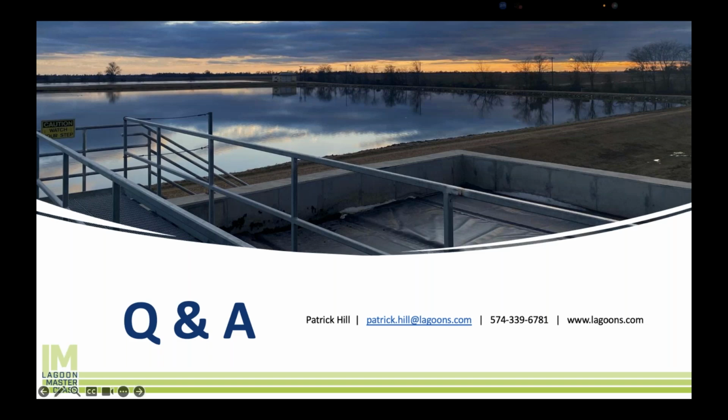From a labor and cost of material standpoint, there is a point at which the time and cost of putting the pond dye in, spreading it around the lagoon, and making sure it gets good coverage over the course of the summer, versus covering a final lagoon as a set-it-and-forget-it approach, you have to start to look at where that cost benefit factors and where the break even is.